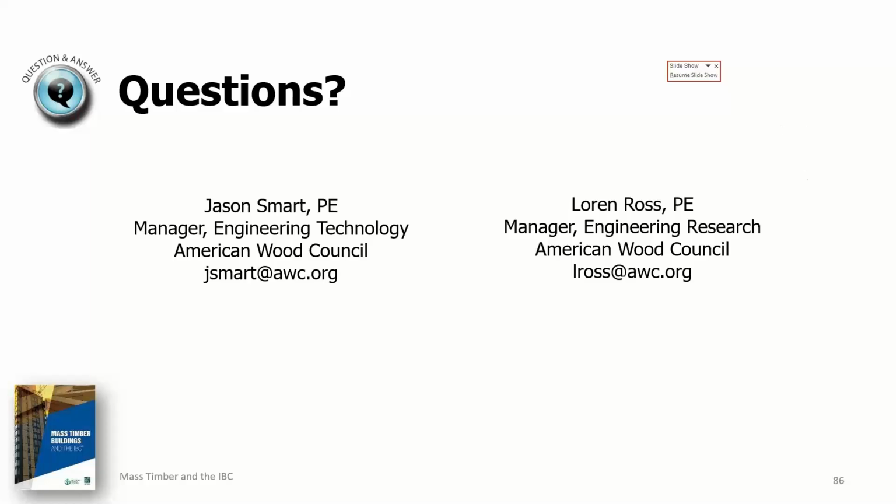Yes and no. It's not explicitly recognized, because of course, what do you mean by intumescent paint? Because those are all proprietary. There's no standard intumescent paint, at least not with a recognized contribution to fire resistance ratings within the code, at least not like we have for gypsum board, for Type X gypsum board. So in that respect, no.